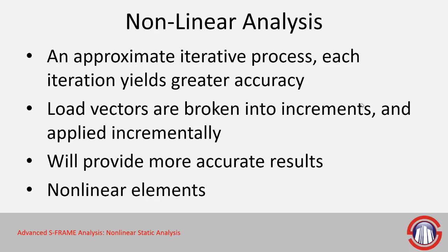Now when running a nonlinear analysis, again, we need to choose the number of increments, or the number of pieces that the load is going to be broken into. And then each increment is going to be solved iteratively until it's within a tolerance. And this is a numerical method, so it's accurate, but it's not entirely exact.